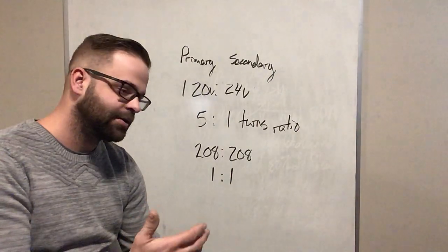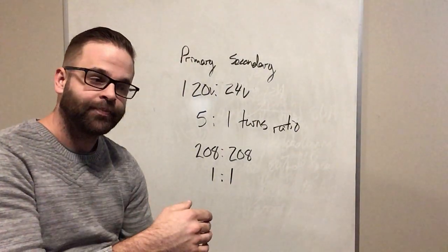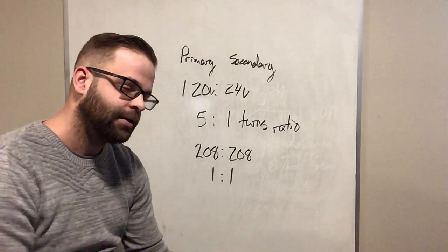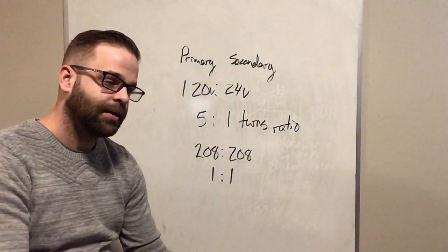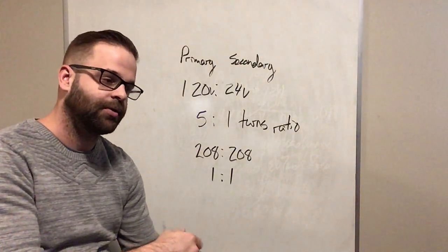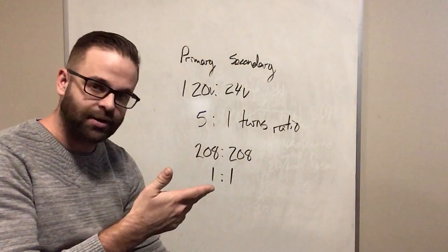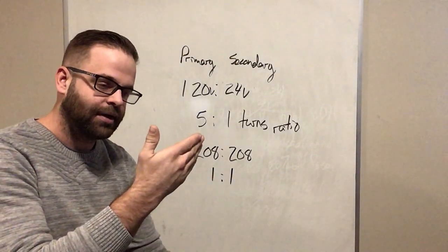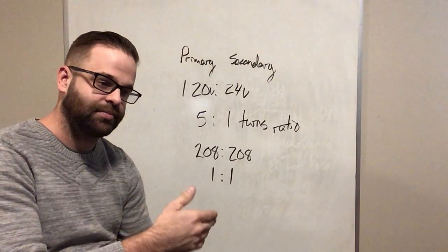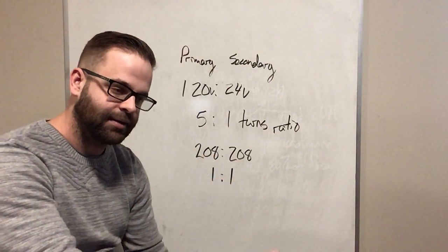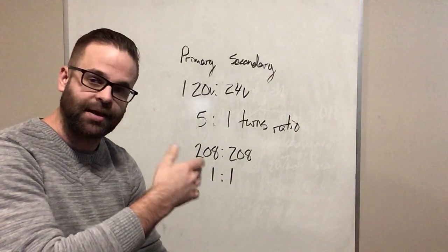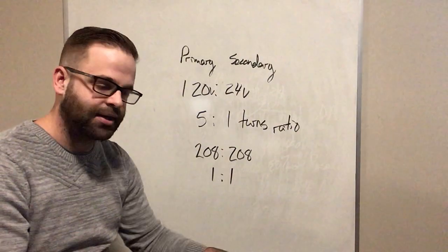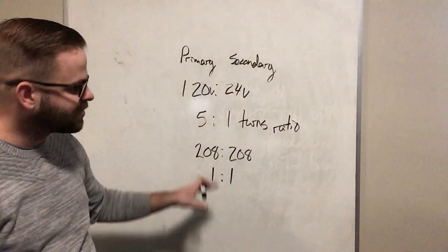Well, if I put an isolation transformer between my main conductors and my audio equipment, then if there's any power surge in the building, or maybe lightning hits the building and is going along the conductors, I don't have a direct electrical connection between that side and the audio equipment, because that surge isn't going to pass through that isolation transformer. Okay, so that's the reason why those would be there.